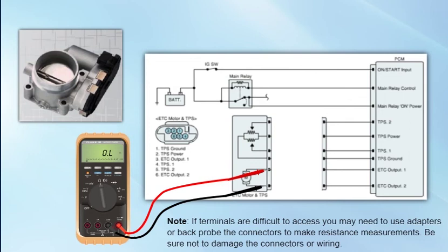If terminals are difficult to access, you may need to use adapters or back probe the connectors to make resistance measurements. Be sure not to damage the connectors or wiring.